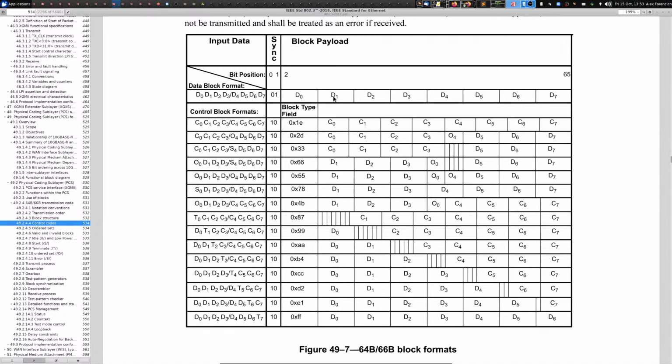Every time we have a lot of data bytes, that's less coverage that you can look at, right? So if you look at, say, termination in lane 7, for example, we have a bunch of data bytes. If we happen to get a bit pattern that sets this prefix and we lock onto that, then all of these are going to look like valid control characters.